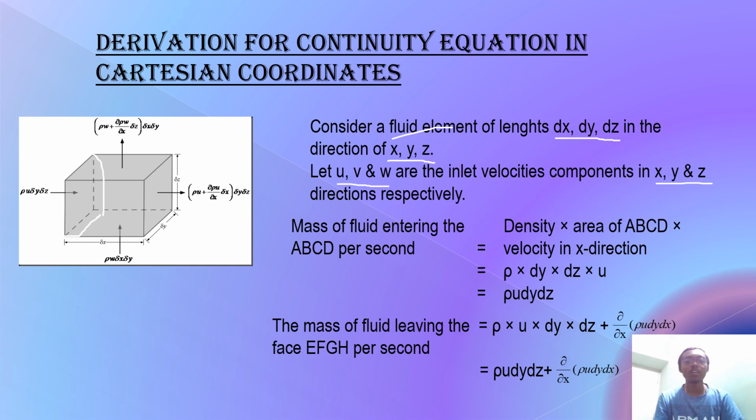Like that, the mass of fluid leaving the face EFGH, which means the face in this direction, we will get the same expression with a small change: rho u dy dz plus the partial differentiation of rho u dy dz with respect to x.